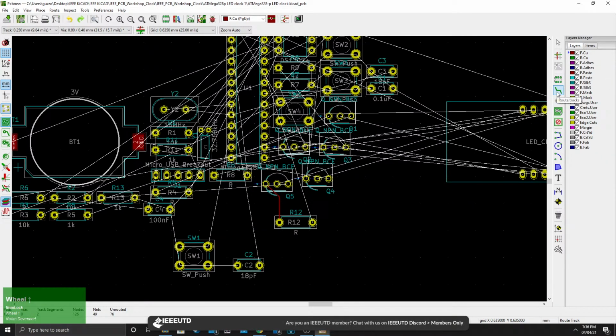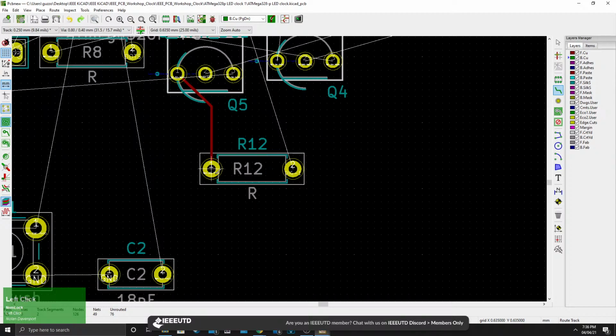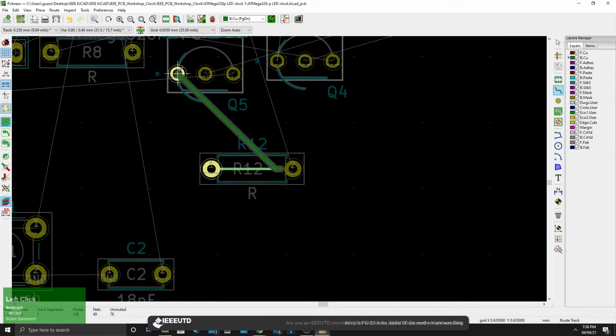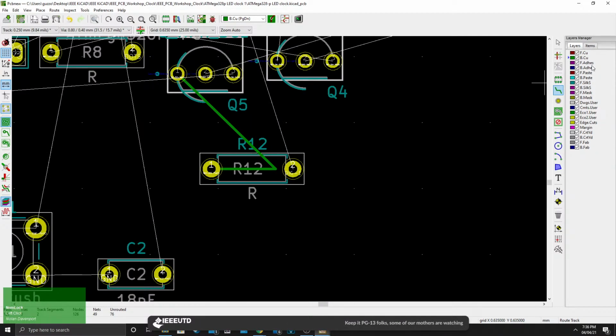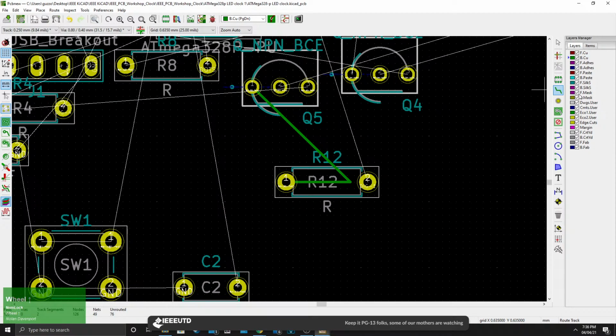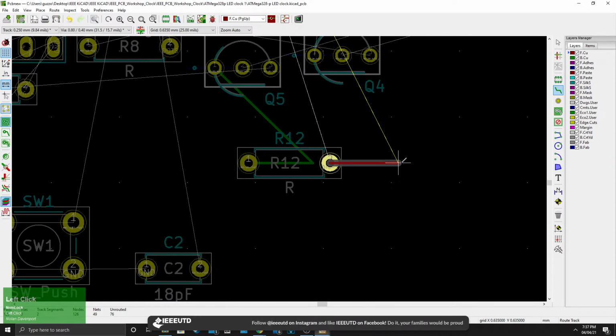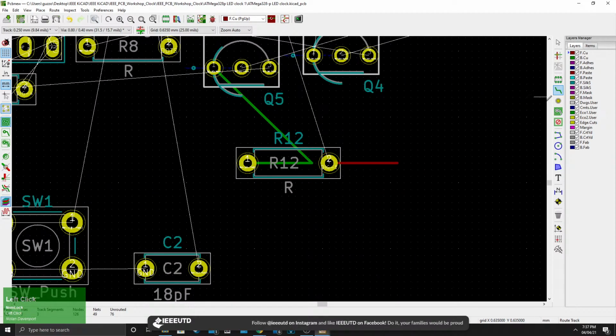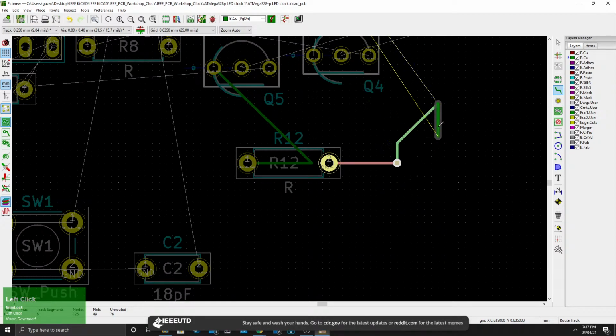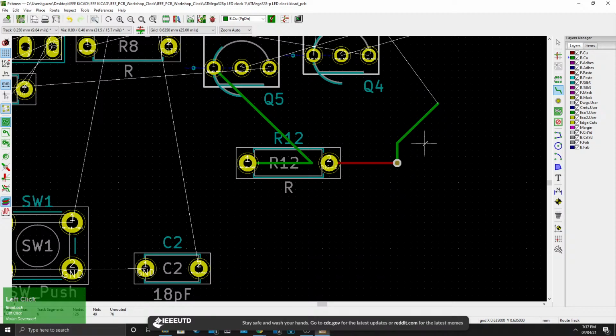So there's tracks, and you can do different layers. As you can see, I can connect those together with it. Oh, and it replaces. That's cool. So yeah, these are the different layers. A via is, if you go here, you can actually press place a via, and that actually allows you to switch to a different layer like that. So that's how that's done. So that's vias.